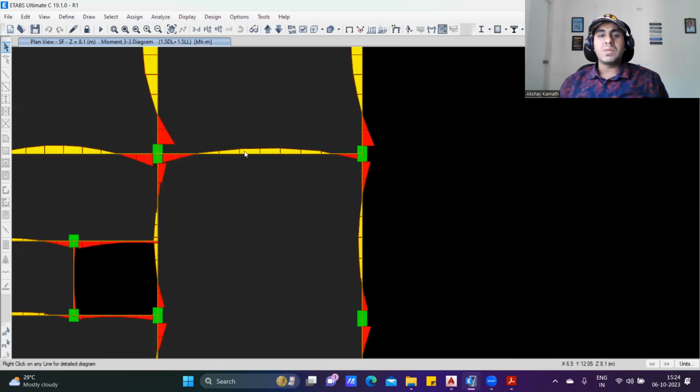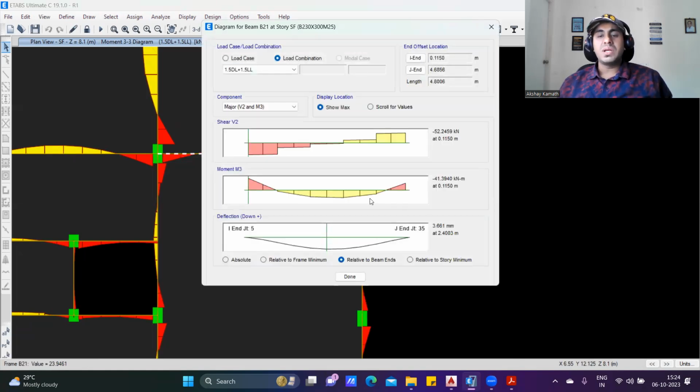Can you see the bending moment diagram of this? For the same beam, can you see how the bending moment diagram looks? This is what we understood initially for a beam. We'll be having a negative bending moment, then it will turn into a positive bending moment, then a negative bending moment. So this is negative, this is positive, and this is negative. Got it? Now this is the shear force variation. Shear force is maximum here, shear force is maximum here, and then the variation will be like this. Understood the concept, how it is? And then this is the deflection you get from there.